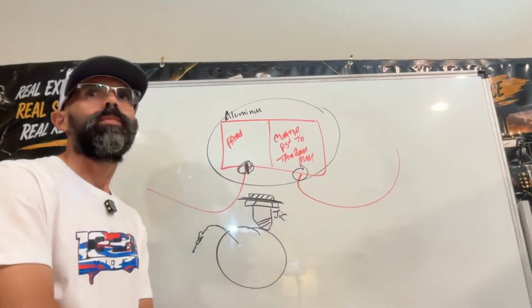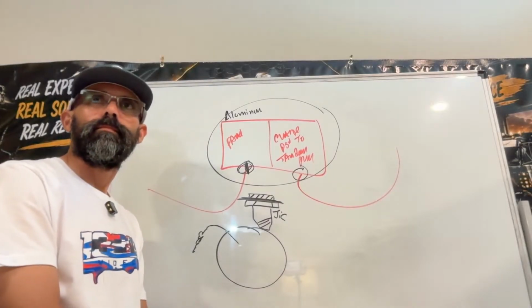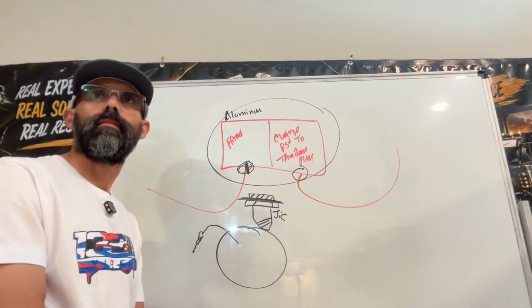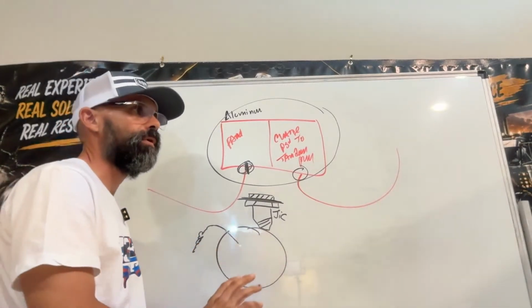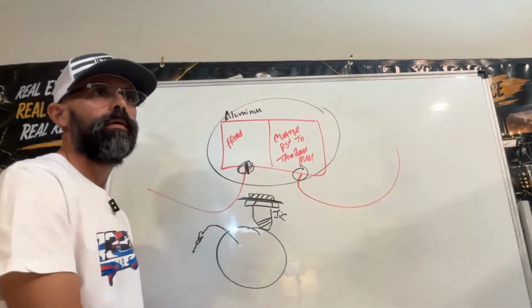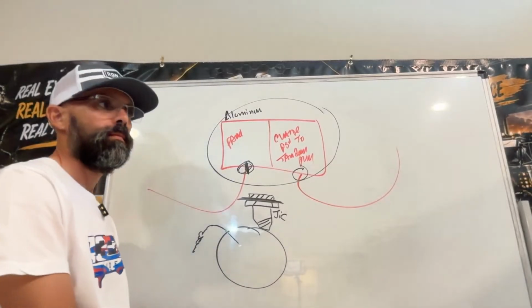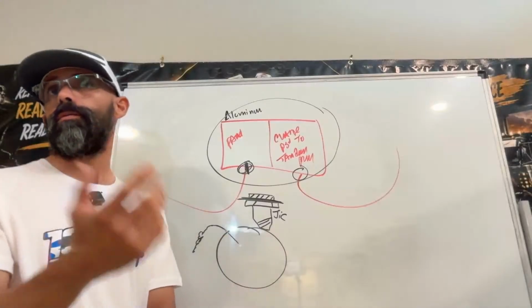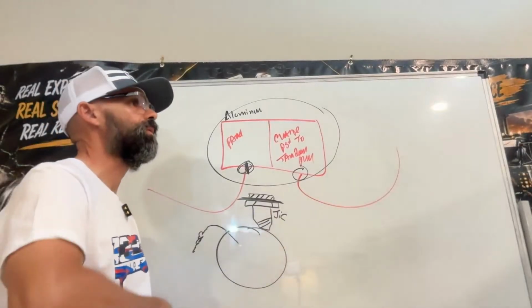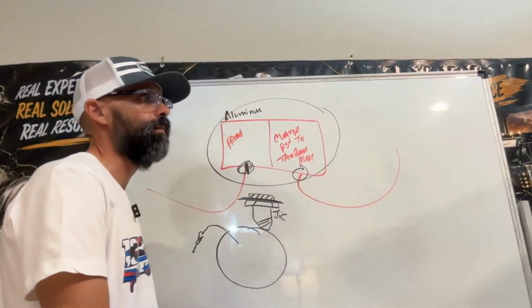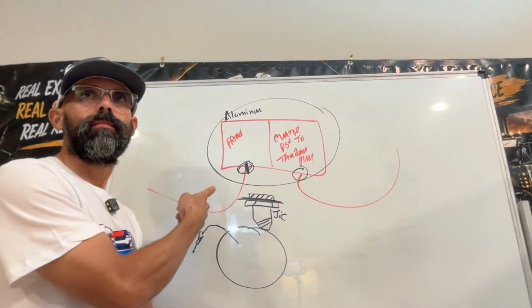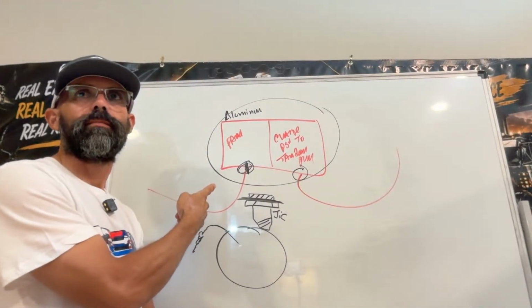You gotta replace the whole pump. And that's the simplest thing. Just do your inspection and make sure that it is not the housing that is cracked. It could be the O-ring, but you keep changing the O-ring, saying, let me go tighten it even more. All you gotta do is pull the pump and make sure it's not cracked.